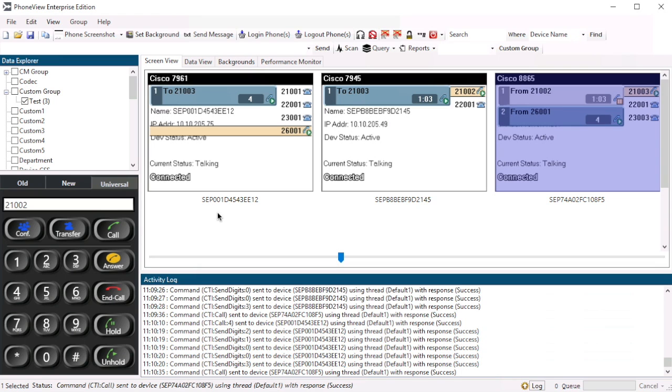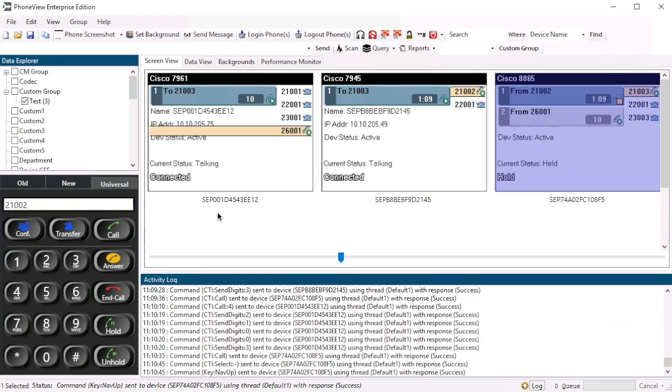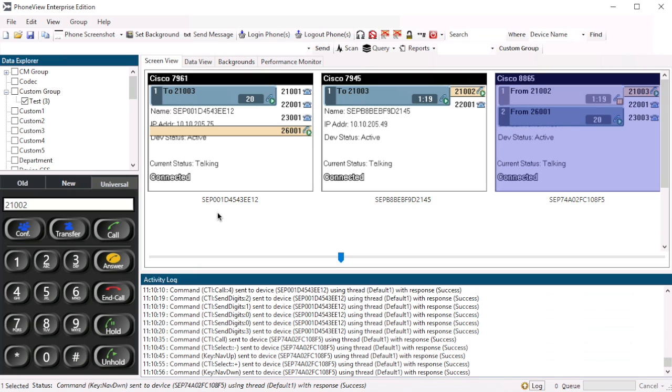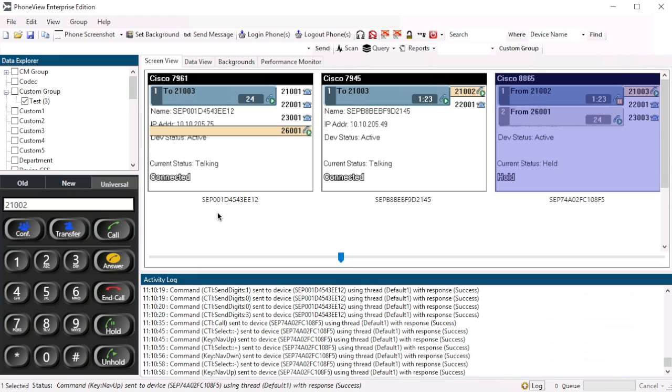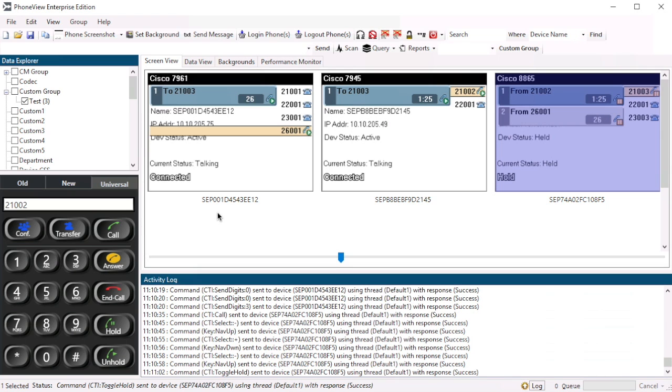And what you can also do is use the up down cursor keys to navigate between connections. So I press the up cursor key, that moves the selection to the first connection. We can toggle the hold operations. So if I move down again, I could do an up again, I can move between them. But if I press spacebar, it unholds the first connection, and you can see obviously automatically the second one gets hold.